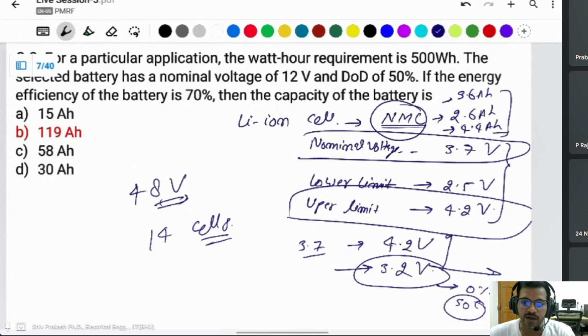For lithium, and all of you know about the lead acid battery. Lead acid battery is very poor in terms of DOD, capacity and density also. In practical cases, a lead acid battery, which uses chemical, has 50% or 60% DOD. On the other hand, for lithium ion cells and lithium ion batteries, DOD is 70%, 80%. Some cells have 90% or 85% DOD. You can discharge like that. But in lead acid, I have only 50% or 60%.